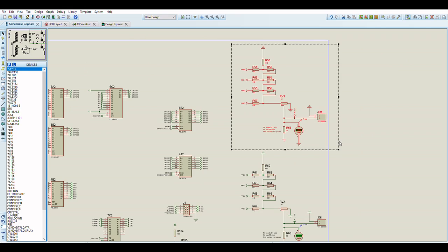The original Bomb Jack hardware resistor ladders were tweaked into this arrangement just because I wanted to make the color signals a little bit more stable compared to the resistor ladders used in the original hardware. The original hardware used a 2N net resistor arrangement, but I was reading up on this, and although it uses, I think, fewer resistors, it can be a little bit less accurate.